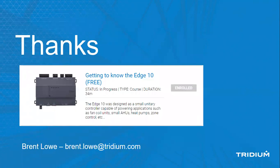The main, I won't call it a limitation, but we'll call it a feature, is that with the Edge 10, the licensing gives you access to 3 devices and 50 points, versus a Jace, which could enable much more, depending on the size Jace that you buy. So as long as those applications work within those restrictions, then you're fine.